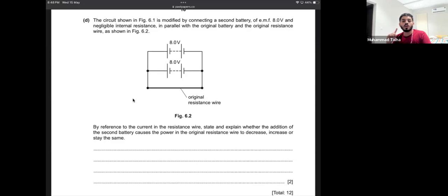See, that's where you're wrong. That's not what would happen. In reality, when you connect cells in parallel, this needs a certain current. Both of these cells would split up the current between them. Let's say if this needed 4 amperes, one cell would provide 2, the other one would provide 2.